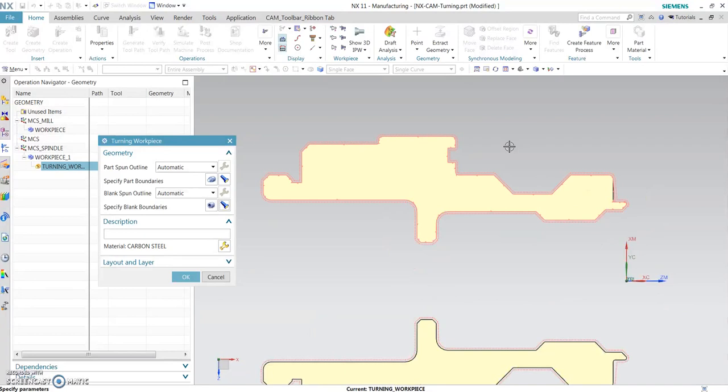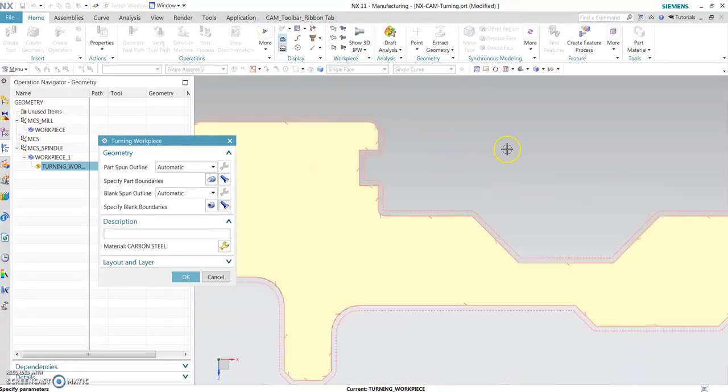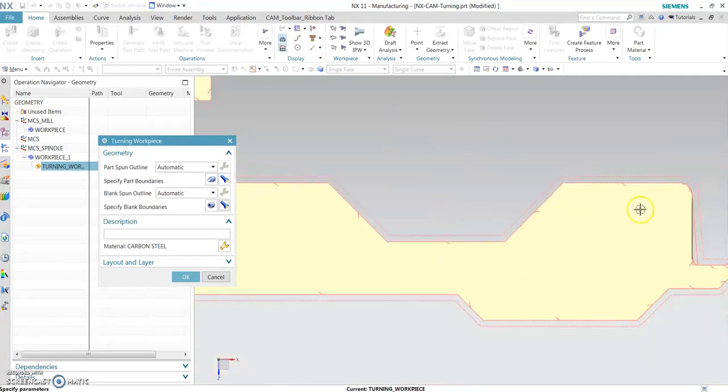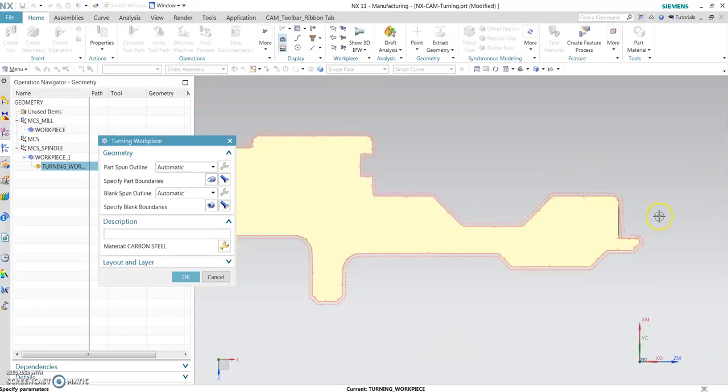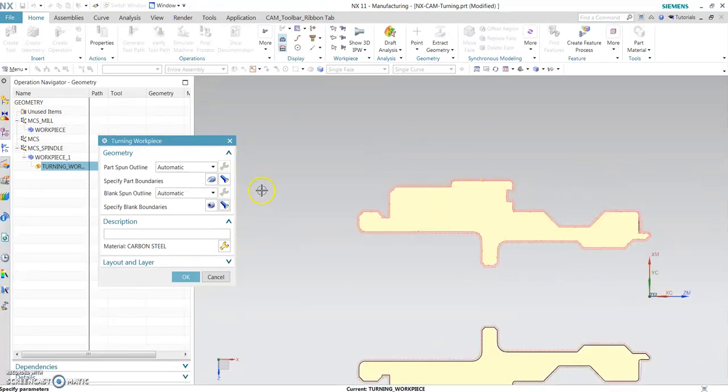It's best to, if you think there's going to be more runout and you need to clean up, or there's porosity, depending on what type of forging. If it's a cold forge, you don't have that kind of problem with porosity. If it's a hot forge, yeah, you may have to give it more stock. Select the gross forging. That's a forged component where you have to do only the medium finish and then a finish pass for the OD, and same thing with the ID.